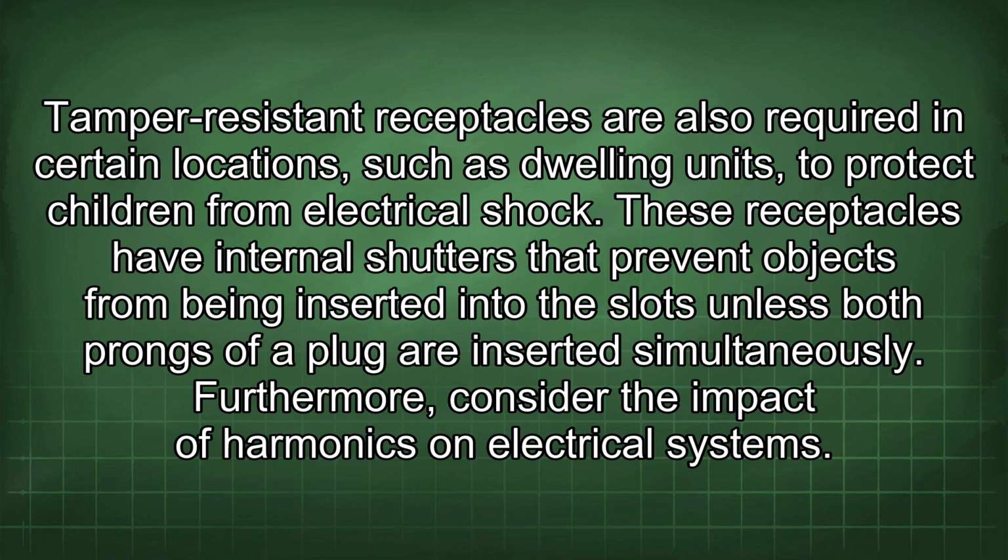Tamper-resistant receptacles are also required in certain locations, such as dwelling units, to protect children from electrical shock. These receptacles have internal shutters that prevent objects from being inserted into the slots unless both prongs of a plug are inserted simultaneously.